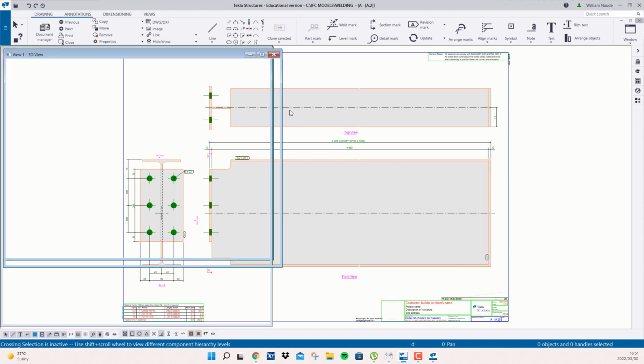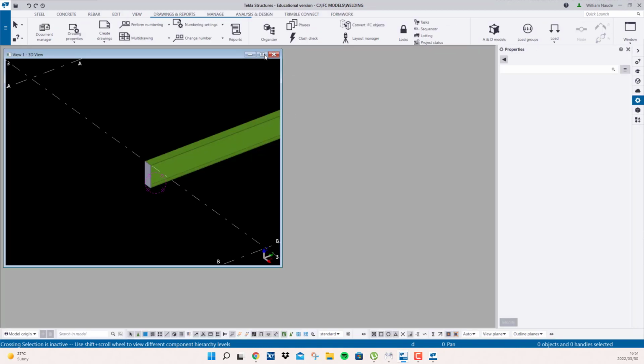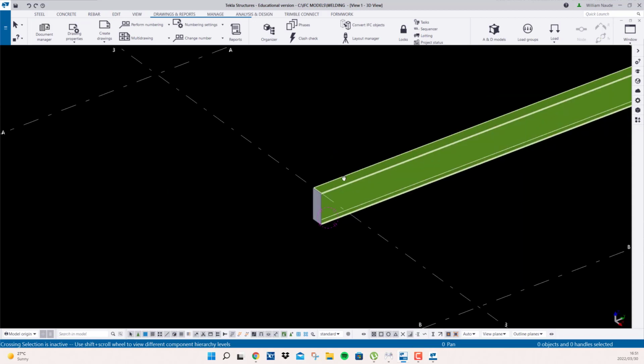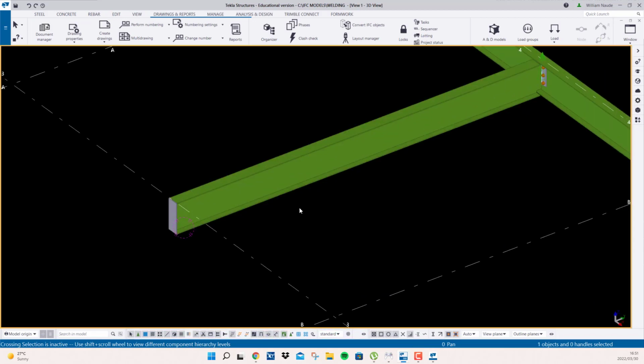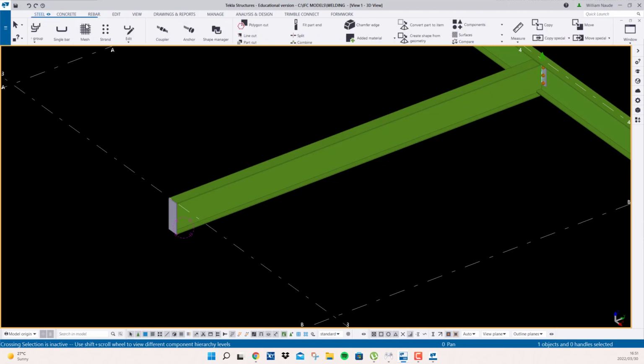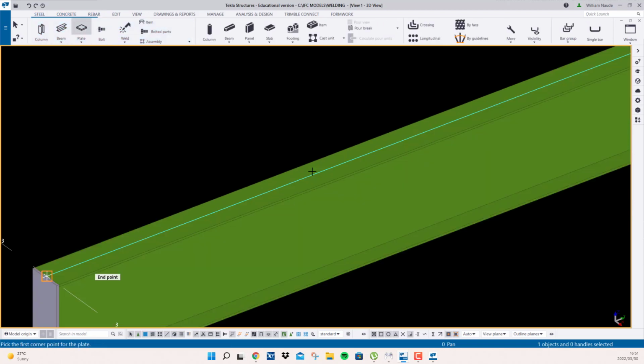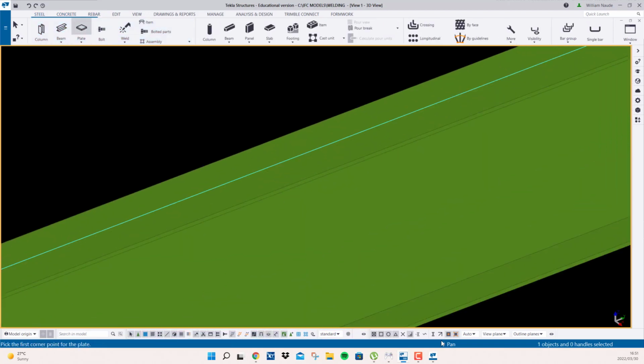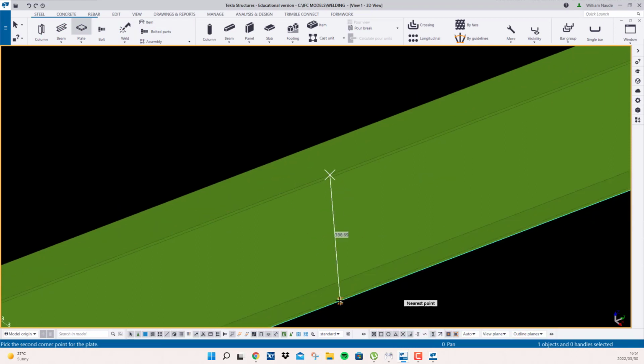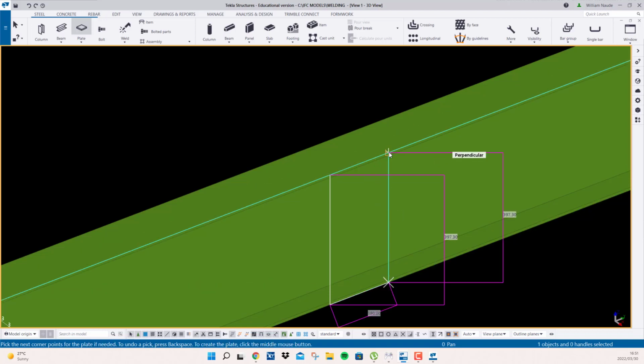This is where it gets a bit tricky, where the macro can actually, especially if you've done a project and you accidentally do this, it can actually mess up your drawings. If I go back to my steel contour plate, for instance, right now I just need to add my snaps on and place it, for instance, right over here. I'm going to place it over here. There we go, and over here.